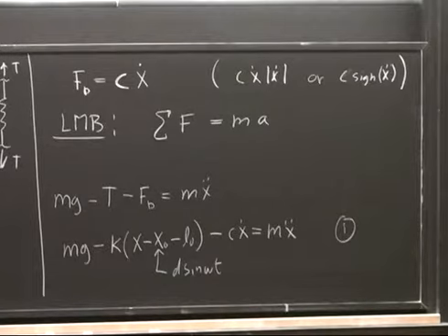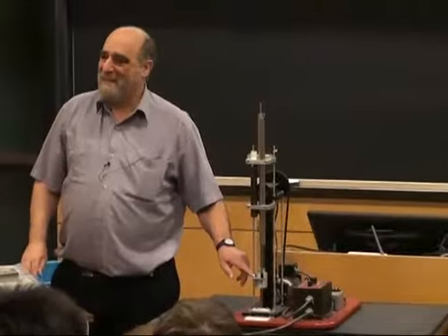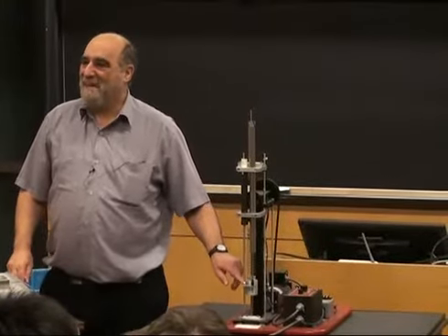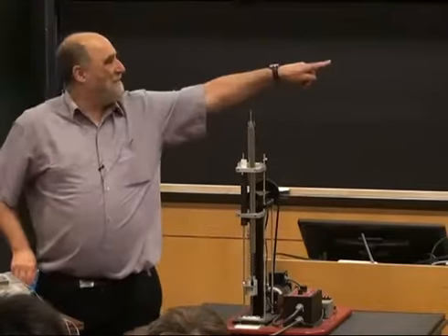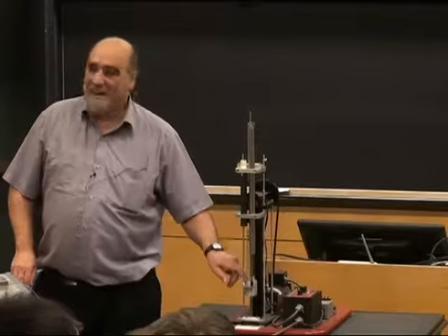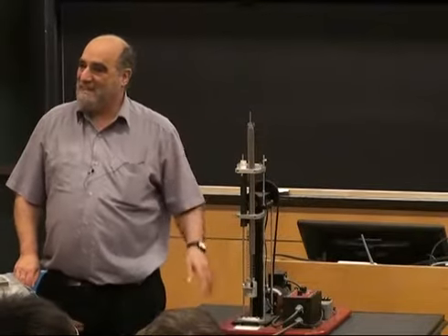Who asked the question? So this system is dominated by sliding friction on this rod. And the sliding friction is more or less independent of velocity. That's the way sliding friction tends to be for dry things. And the most accurate model for this system is probably the last one of those 3. If this wasn't sliding and it was moving in air, the more accurate model is probably the quadratic drag, because this is a big, fast-moving thing.